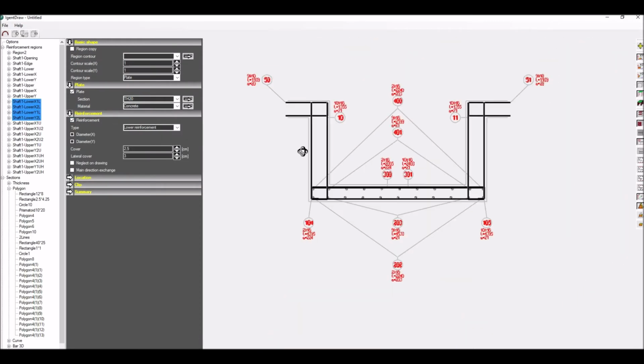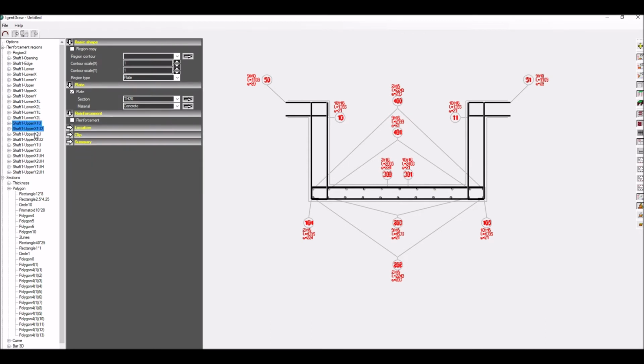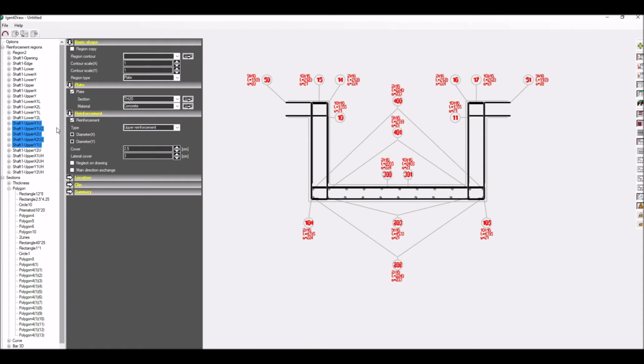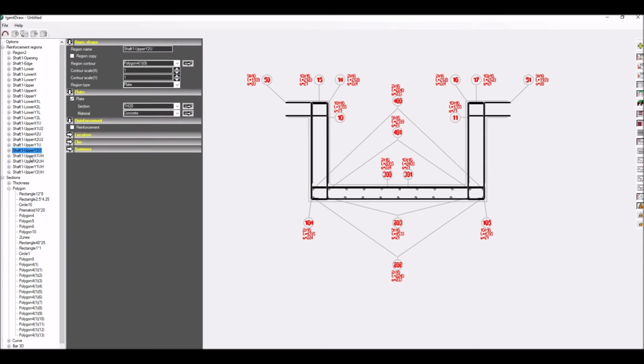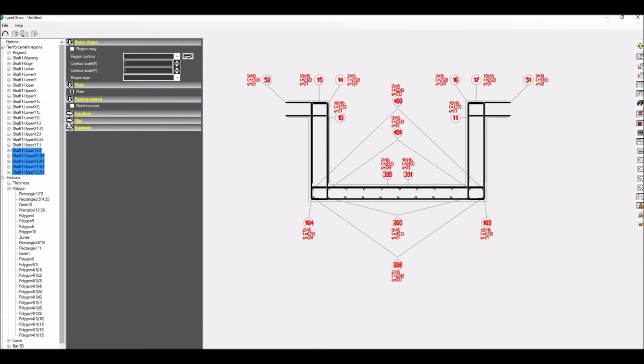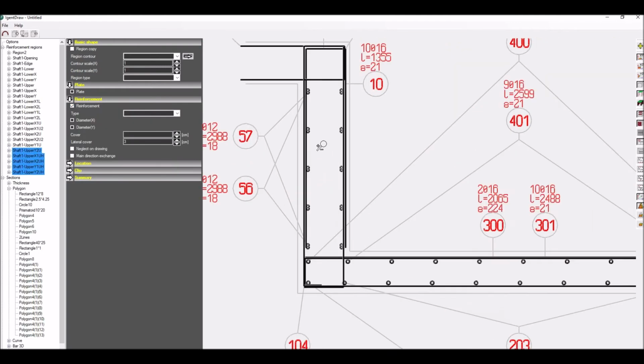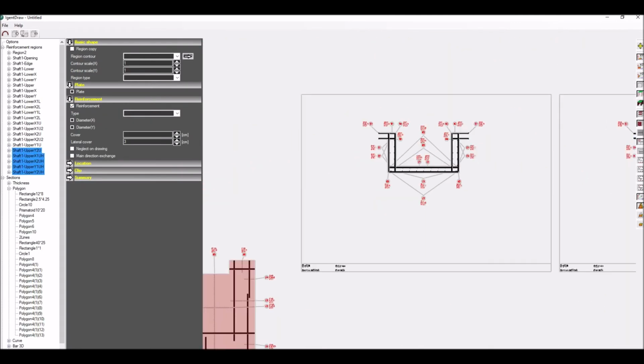Then L-bars are generated on each opening side. It is possible to complete vertical wall reinforcement by U-bars placed on the shaft top. Horizontal wall reinforcement is composed of U-bars which are overlapped respectively.